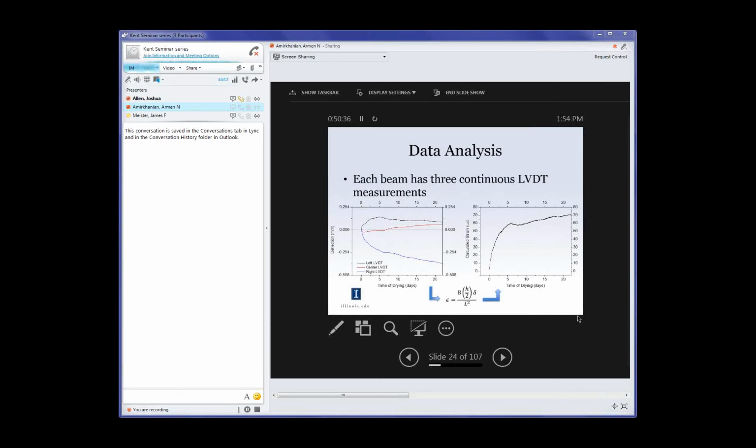So let's say mix A has half the curling strain according to this model as mix B. If we take those two mixes and put them in identical situations in the field, let's say a doweled, 10-inch slab, we would expect to see similar results. Mix A would have less curling than mix B. It may not be half because, like you said, there's self-weight and all this, but it should most likely be less. Yeah, so I have no questions about that.